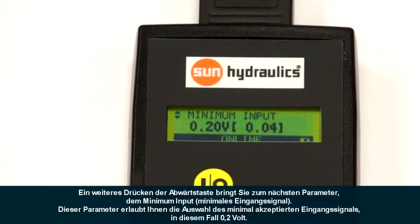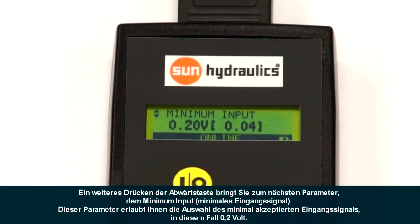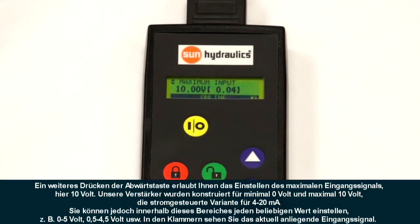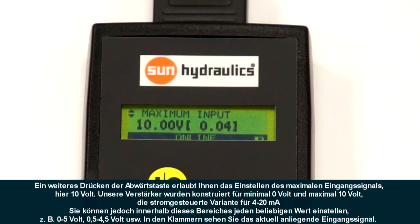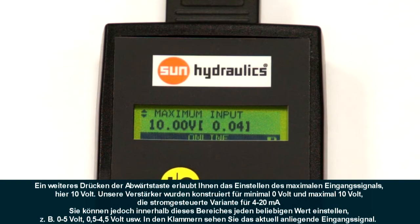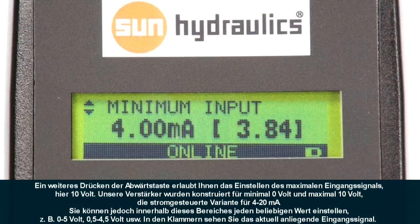This parameter allows you to set the minimum input from your command signal, 0.2 volts in this case. Pressing the down arrow again allows you to set your maximum input, 10 volts in this case. Our amplifier is designed for a minimum input of 0 volts and a maximum input of 10 volts. However, this can be adjusted to any value in that range. For example, 0 to 5 volts, 0.5 to 4.5 volts, etc.